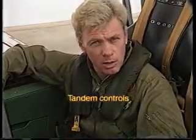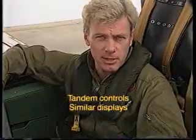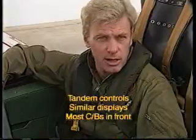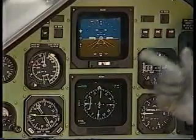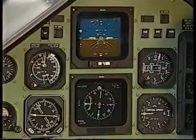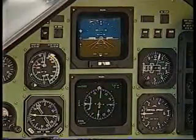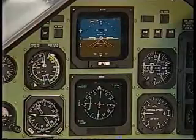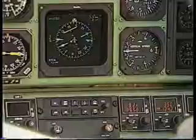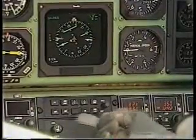All of the controls operate in tandem, so whenever a selection is made in one cockpit, it appears on both sets of the instruments. The only difference between front and back is the circuit breaker panels, which are mainly located in the front. The EFIS system consists of two display screens, the electronic attitude indicator, or the EADI, and the electronic horizontal situation indicator, or the EHSI. The EFIS control panel and the oblique heading select panel are located here immediately beneath the EHSI. There is also an EFIS swap button here, under COM2.